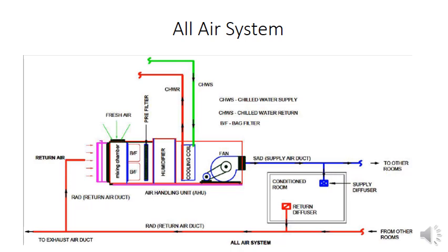Now this supply air can be circulated to other rooms as well, if it is being used for multiple rooms or multiple buildings. Similarly, that supply air duct can be used to supply heated air in case of winter, to provide the required amount of sensible and latent heat to the conditioned space. The duct that supplies air into the space is known as SAD, supply air duct, and the return air duct, which is RAD, is used to carry out the used air.